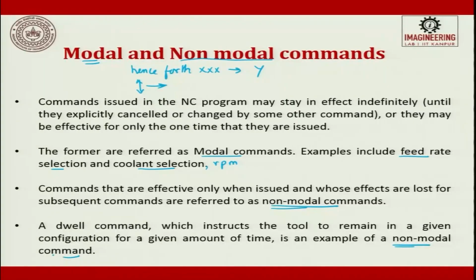In the same way, you can also use some gauging devices to check whether the features made are perfect or not. So, here what we do, we write a program, we call that gauging device and we say hold the machine for 20 seconds until that gauging system gets activated, gauges the feature generated and says go, no go, that means whether to go further with machining or not. So, those commands are called non-modal commands. So, the important thing is modal commands and non-modal commands.